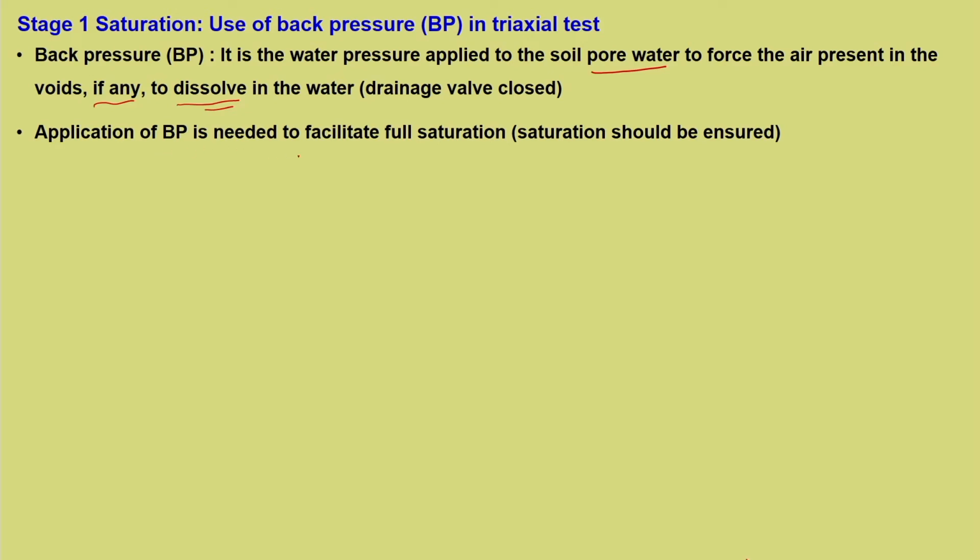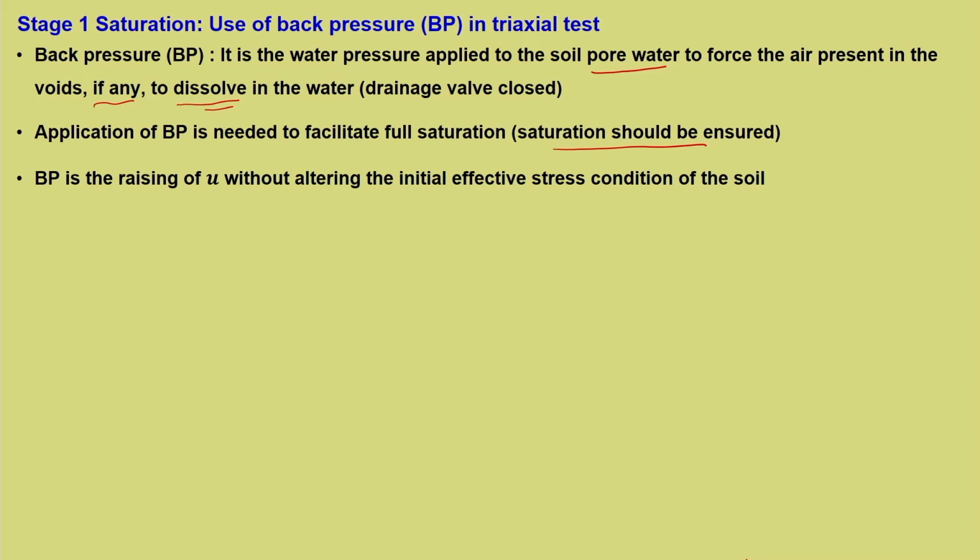Application of back pressure is needed to facilitate full saturation, and saturation should be ensured. So, it is the raising of pore water pressure without altering the initial effective stress condition of the soil. This is very important. The moment it changes the effective stress, it is going to have its effect on strength.